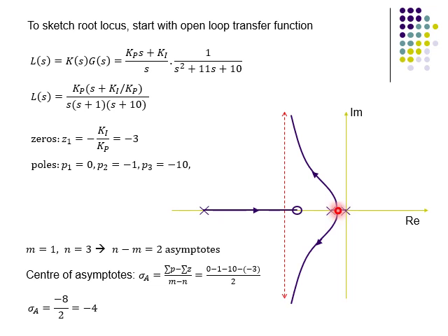So that means that the two poles must have equal value, which means that the two poles would both be at the breakaway point here. And remember, for this system it's a third order system, so we've actually always got three poles, and if the two poles on the right are at the breakaway point, the pole here on the left will be somewhere along the branch here, but we don't know exactly where. But we can now try to find the exact location of the breakaway point and the corresponding value of Kp.